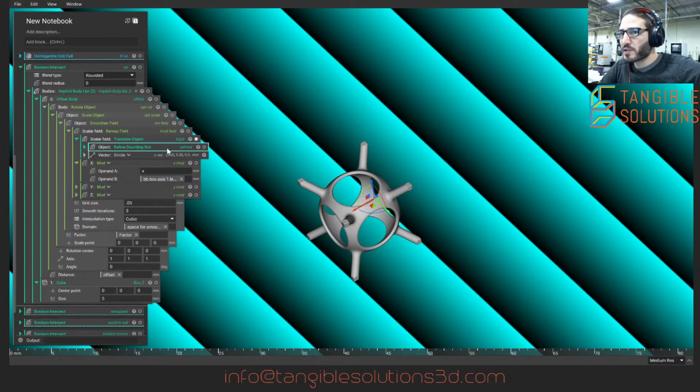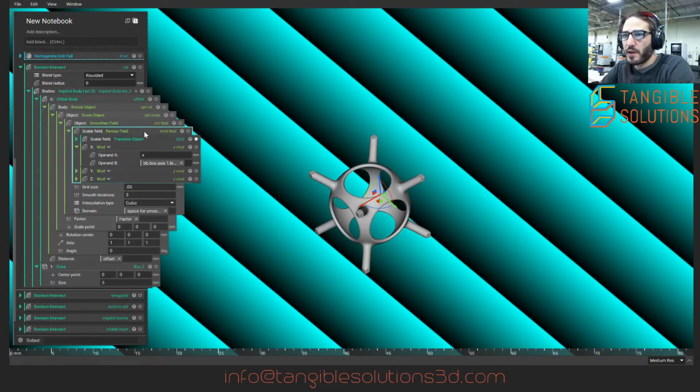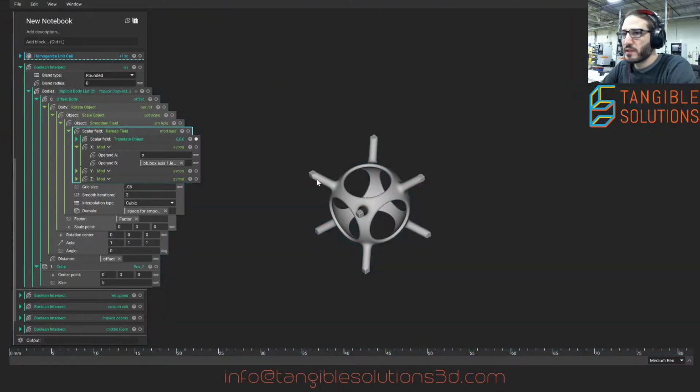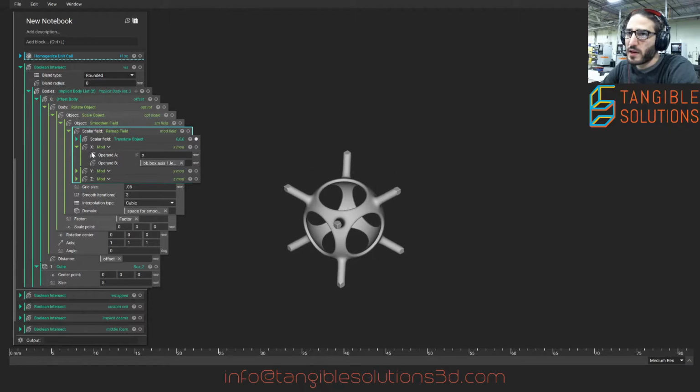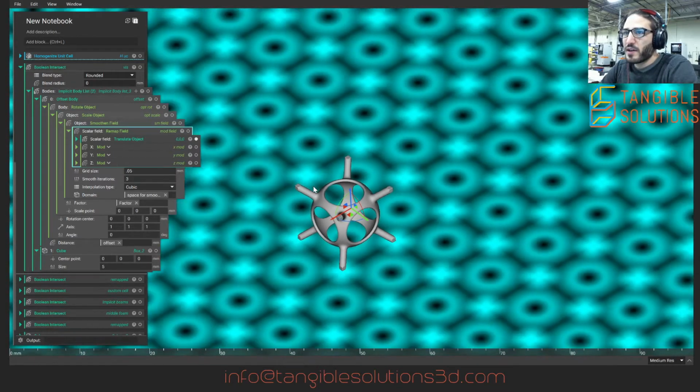And so the most robust way that I found is to center your unit cell about 0, and then translate it by half of the side length using a vector. And that's going to give you, again, your seed for your field. So then we're going to perform a remap. Again, this video isn't the time to go through in detail what remap is, because I could ramble about it if I wanted to.